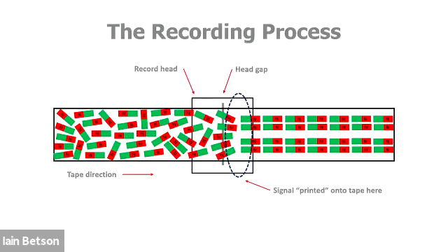Although it's the head there, I put for clarity purposes two tracks. The white areas either side of the two tracks would still have a random oxide, because that is unrecorded: guard band areas between the two tracks, or fringes at the side. But that is where the recording process happens on the tape, just after the head gap as the tape runs past the head.